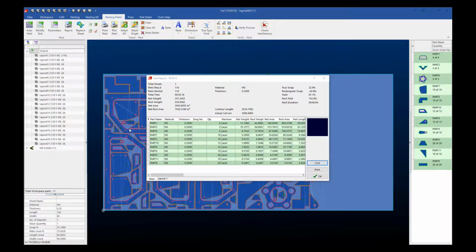But for instance, if I was on my plasma machine, I might want to do a time calculation for when I'm cutting 1/4 inch with 120 amp versus 150 amp, and getting the two different time calculations there and having those dialed in depending on which amperage that I'm using. So there's a lot of different variations as far as the different materials can go, so it's very important to make sure you take that into account.